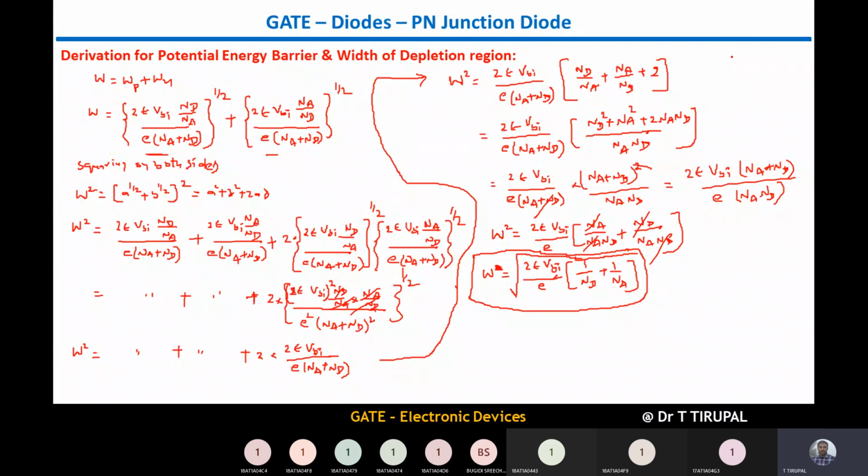This built-in potential here, you can assume, if this is the diode, P-type and N-type semiconductor, this is the depletion region. And what is this depletion region barrier height? It is always given by V0, as I have discussed already in the first class. This is called barrier height for P-type. If a hole wants to cross the junction, then it has to overcome this barrier height V0, right?